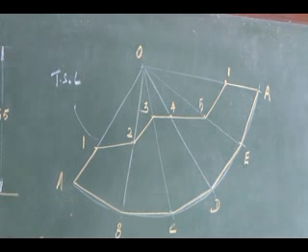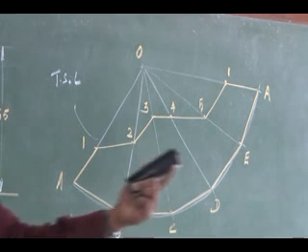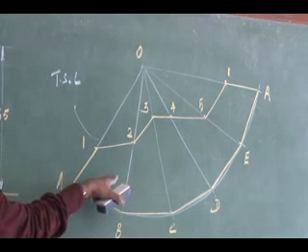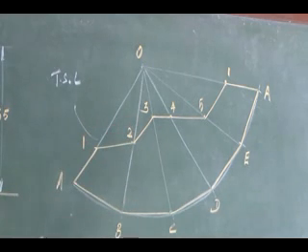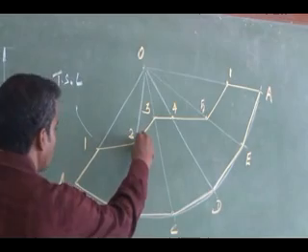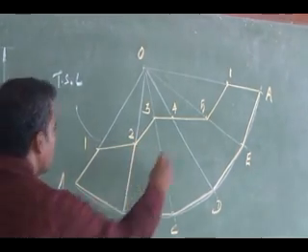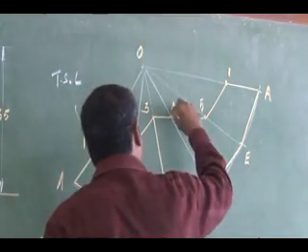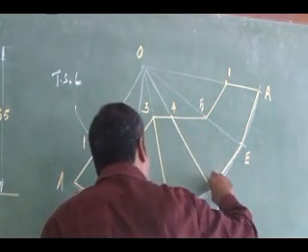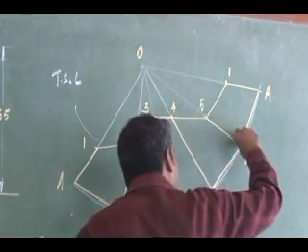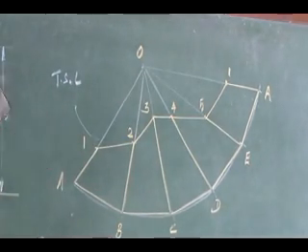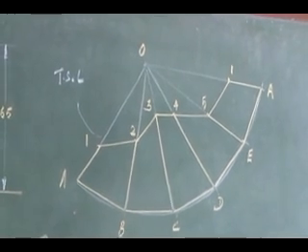Only for a cone you don't have an edge, only a generator; you need not show the generator by darkening. Here I have a distinct edge. That edge should be darkened. So you darken B to C. So this is my final lateral development of the retained portion.